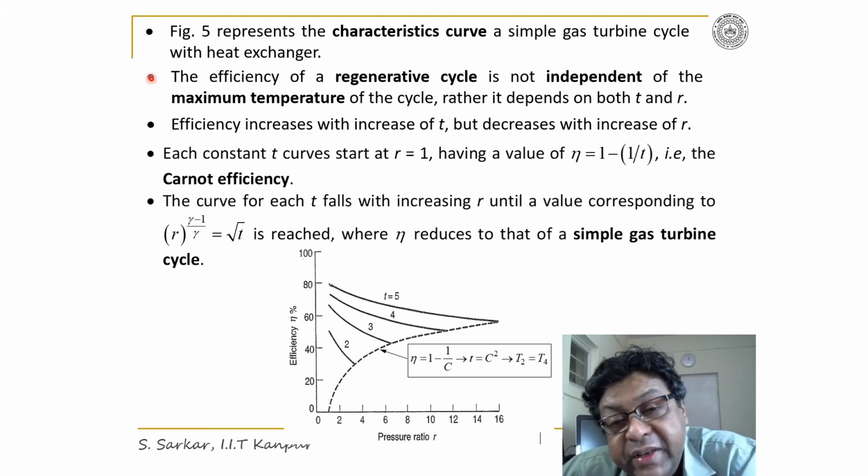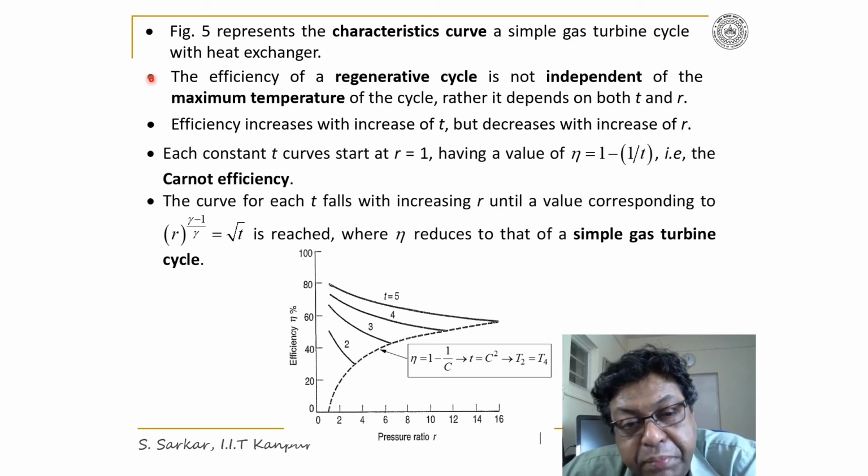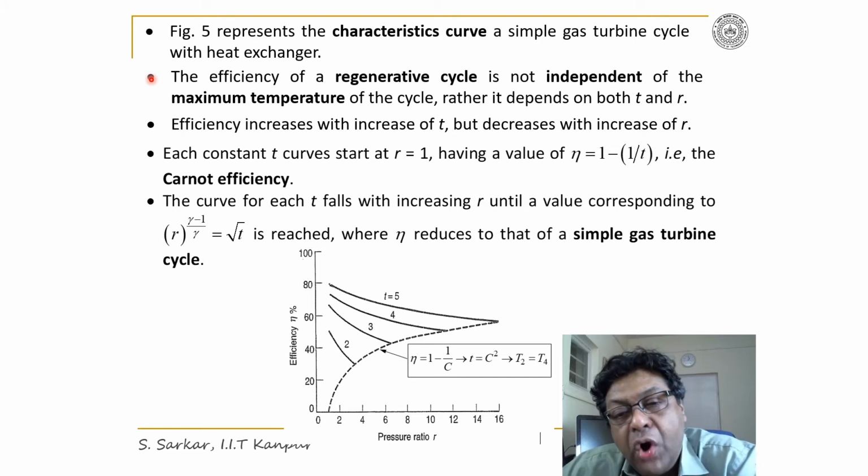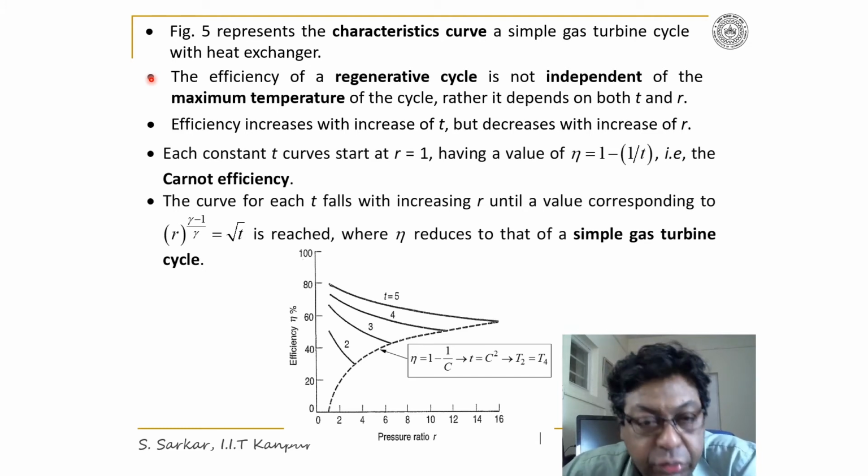Here, efficiency is not independent of the maximum temperature of the cycle. Rather, the efficiency of a regenerative cycle depends on both temperature ratio and the pressure ratio.